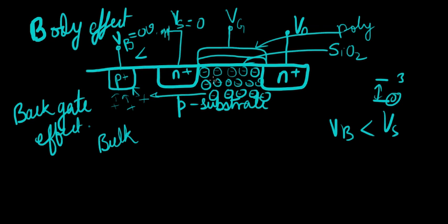But in the first place, if you paid attention to the threshold voltage lecture, these negative ions are here because of VG's positive voltage, correct? The collection of positive charges around this area repels the positive charges from here and leaves us behind with these negative ions. And they also have to be in balance. Basically, they have to mirror the charge coming from the gate.